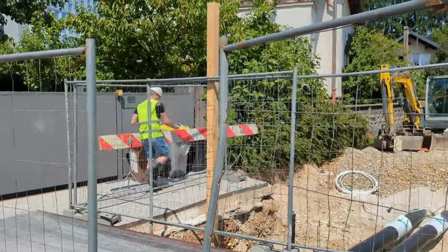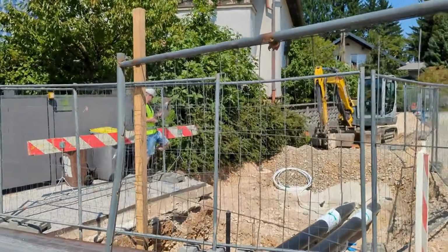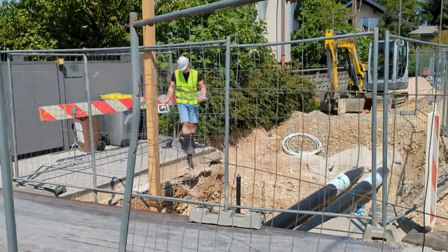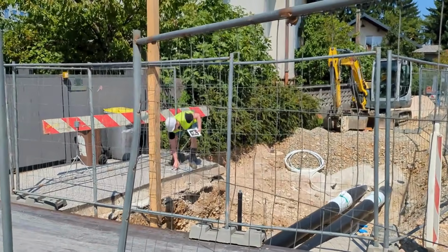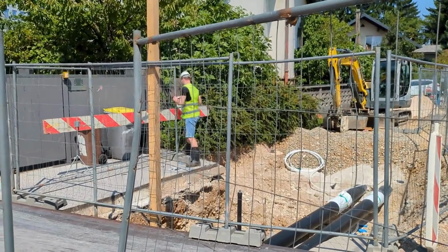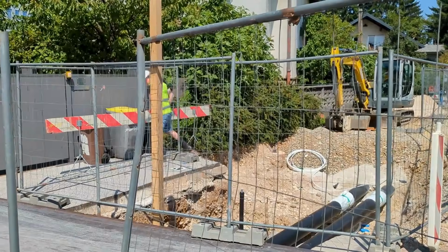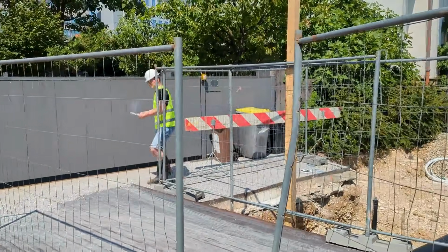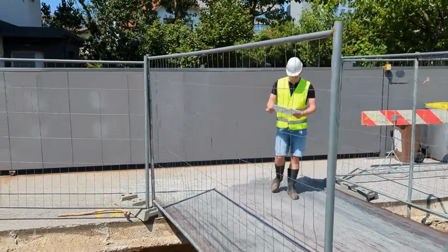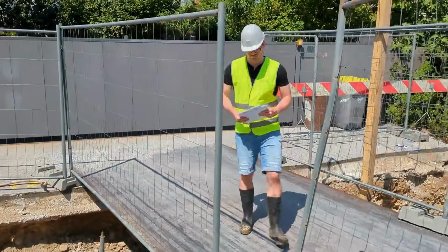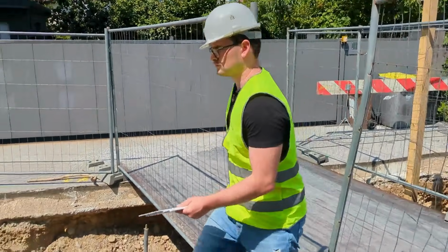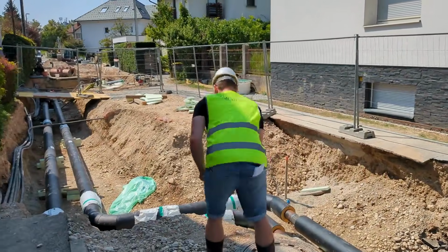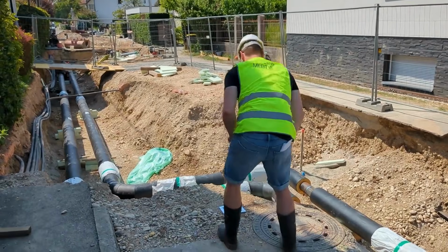As Ivan already explained, first we need to lay down the ground control point targets, in this case April tags, because they are automatically recognized, so no manual work during the orientation step in 3Dsurvey. Of course, we need to place them before we do the recording, because ground control points need to be on the video and later on in the extracted frames before we calculate our 3D models.